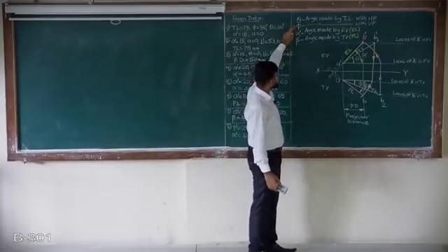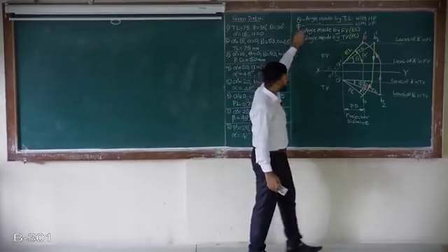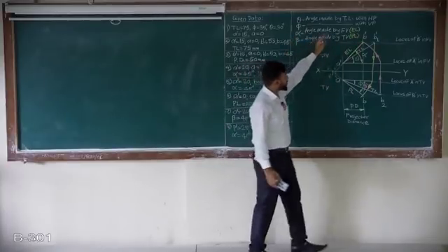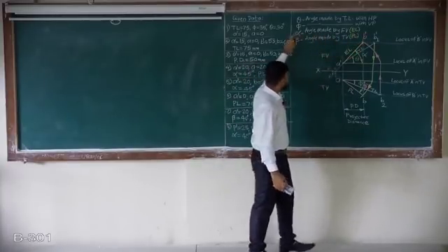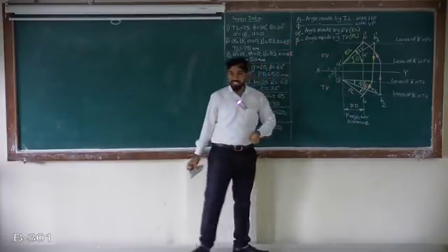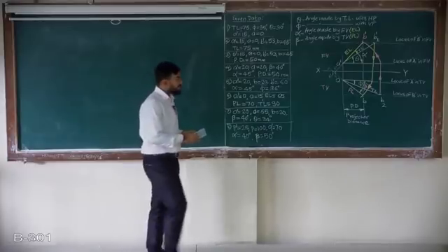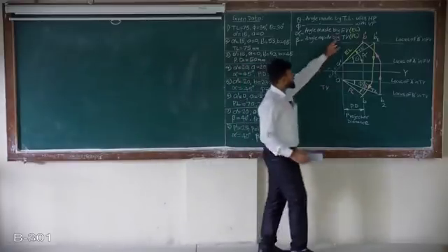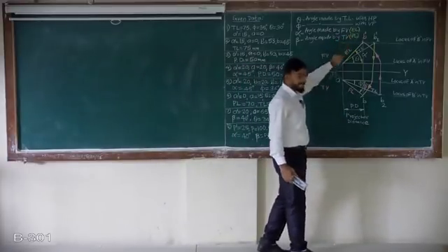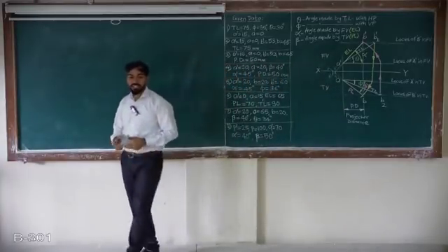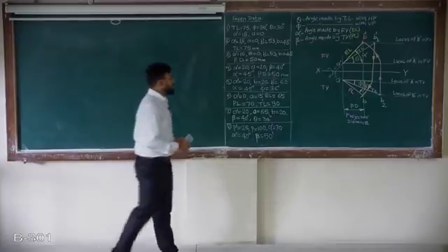So first, this is theta, angle made by true length with HP. Second, phi, angle made by true length with VP. Alpha and beta, they are apparent angles, that is angle made by apparent length, that is EL and PL. Front view as elevation length, top view as plan length. So what is true length? True length is the actual length of line.